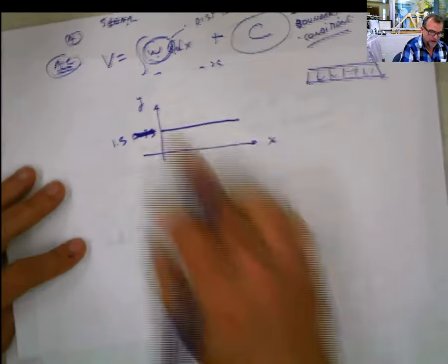So if you go to the shear diagram at C and read that point, how much is it? 0.75. And now you just solve this and say V equals 1.5 integral of dx is x plus 0.75.